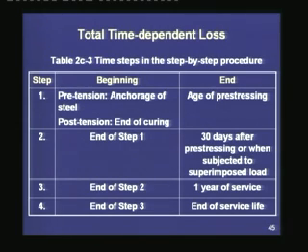If the pre-stressing is done right after the end of curing, then we may not consider any long-term loss in that first time step. The second time step starts at the end of the first step, that means it starts at the age of pre-stressing and it ends at 30 days after pre-stressing or when subjected to superimposed load.